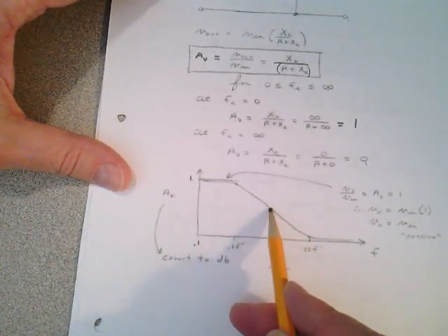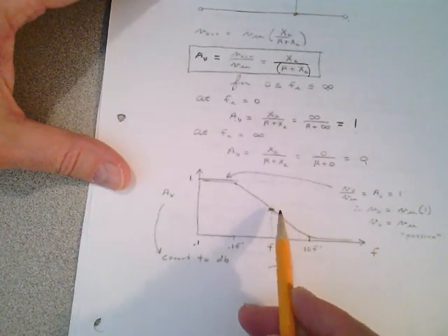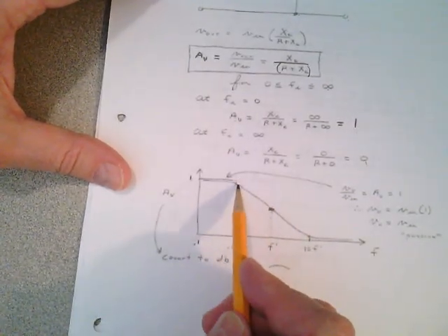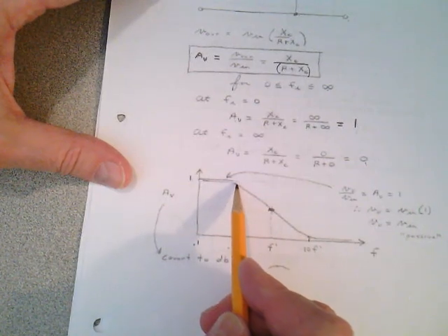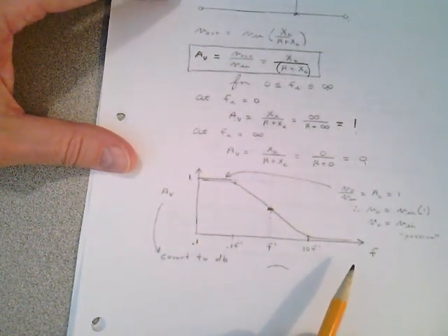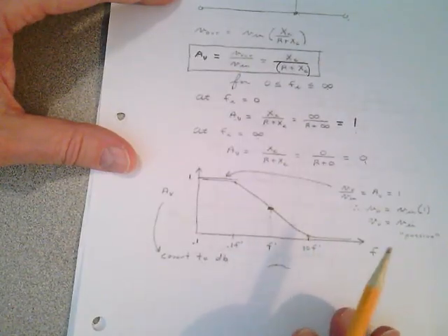A good rule of thumb, and you'll find this out later, is you go 1/10 of a frequency down, and the effect of that filter has already reached the point that it's not going to make any more additional change to that circuit.